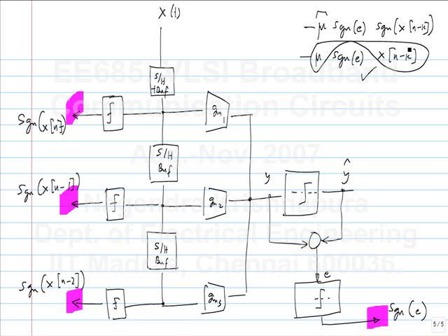The current which comes out of what? This one. This is xn times GM1, yes. In one case, the GM1 is simply incremented or decremented by mu. That can be realized by having a GM which is switched, right? Just like we discussed for the transmitter, you can imagine GM being made of a number of cells which are connected in parallel.